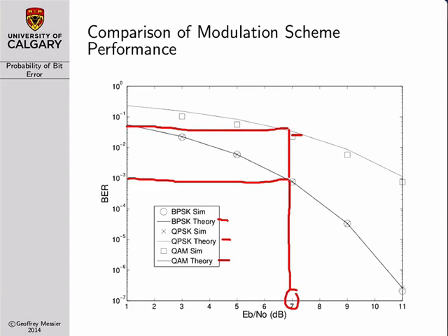The reason why we were able to get such a significant improvement is because we used the second orthogonal basis function, basically. However, when we go from QPSK to 16 QAM, again, a doubling in throughput, just like the BPSK to QPSK transition, we no longer introduced any additional signaling dimensions, right? We just had to pack our signal constellation with more points.